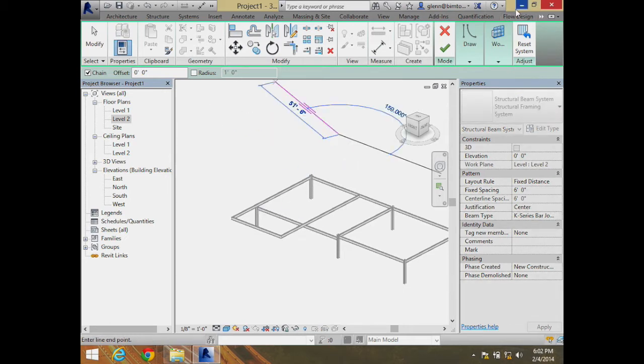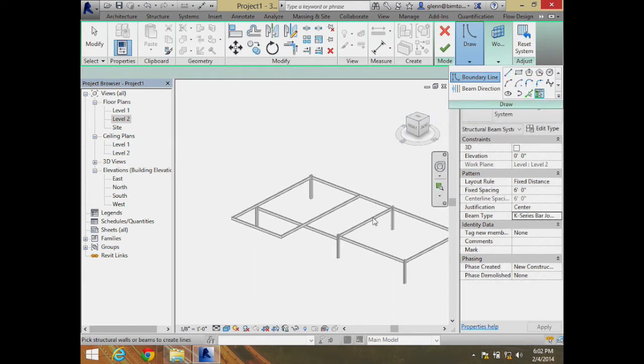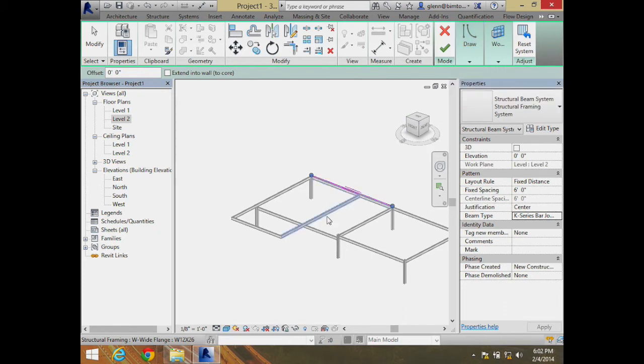And then we go through and, it's a little hard to see because my screen is squishy. I'm going to draw a boundary. In fact, I could even pick the boundary. What I'll do is pick this column, or this beam over there, this beam over there. I'll just do that little section right now, and I'll have to trim that. The little triple line there, the parallel lines, that's showing us the direction that they're going to run. Let me trim it up and show you how it affects it.